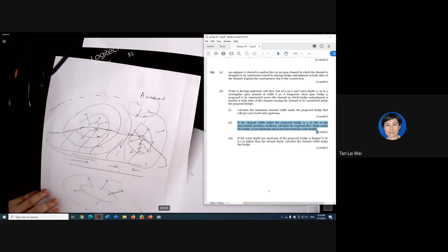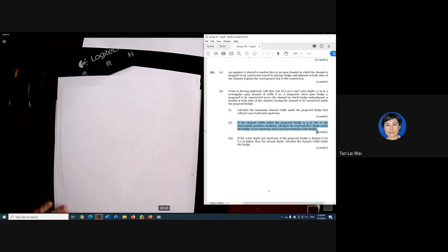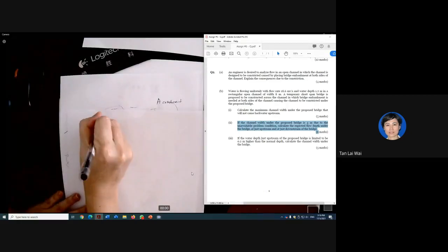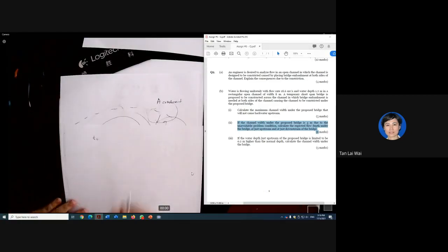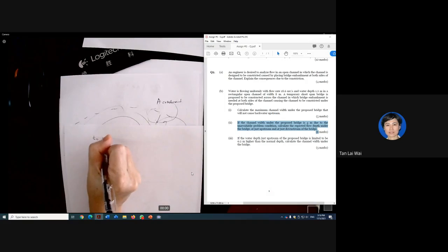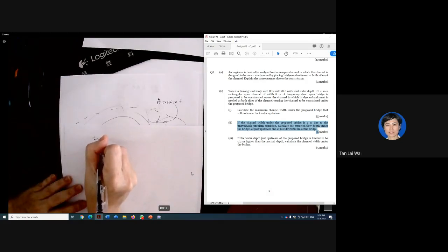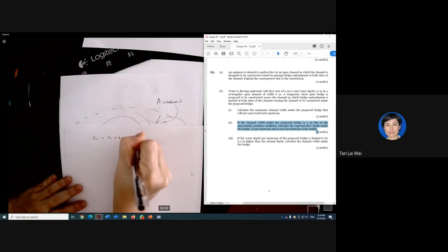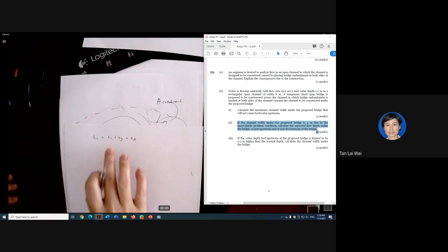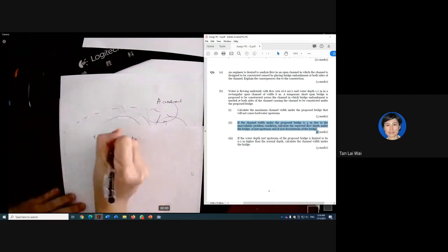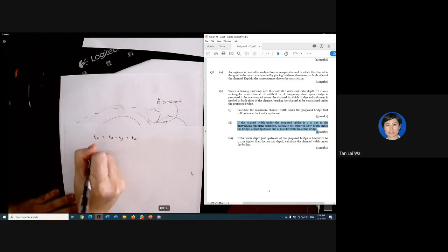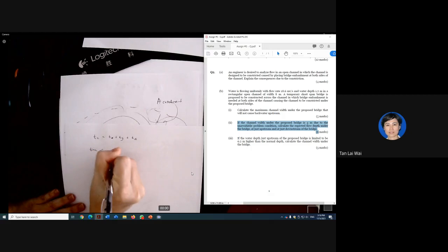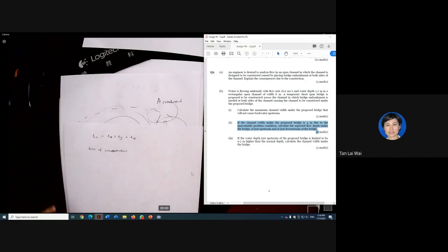There's another thing that I want to explain to you, which is TC. It's just 5 minutes. Time of concentration, TC. If you look at this Urban Stormwater Management Manual, or MASMA, Manual Saluran Mesra Alam Malaysia, TC is equal to T0 plus TG plus TD. It doesn't matter, it could be T0 plus TD plus TG. So TC would be time of concentration. It actually tells you something about the name.